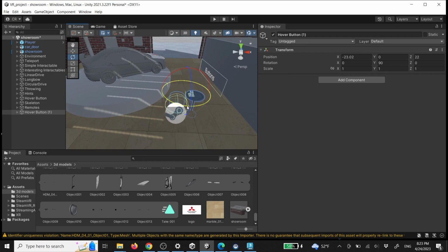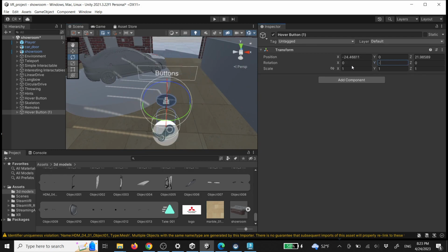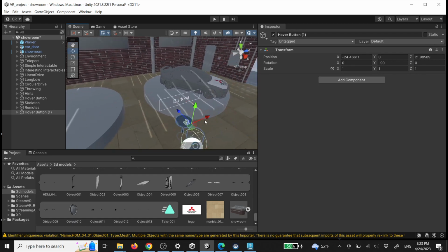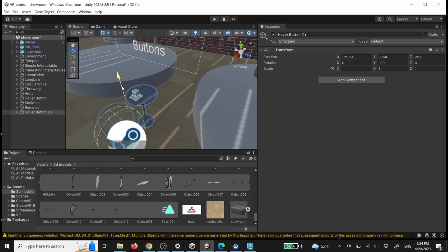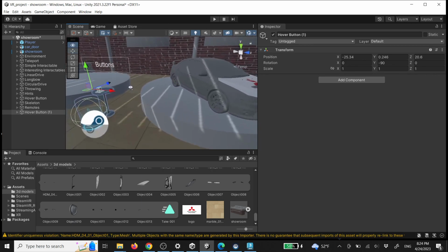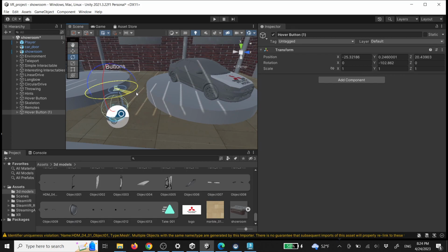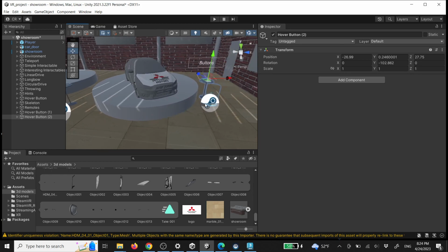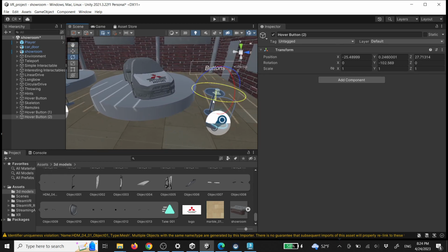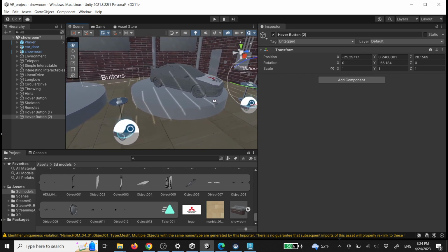We're gonna see that we will also have to rotate this, so minus 90 degrees. And I'm gonna position the button. I'm just gonna move it in those two axes, so over here, and after that a little bit on the y-axis, so that the button will not hover, so like that. I'm gonna slightly also rotate it, and if you want to duplicate again, you can press Ctrl D. This will again do a quick duplicate of that button. So those will be the two buttons.